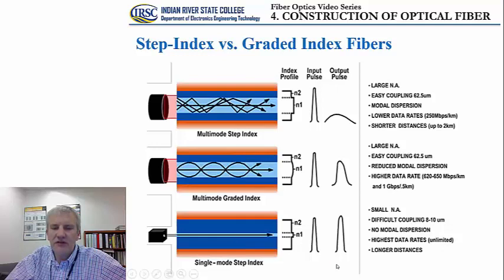The simple reason for that is that in the case of a single mode fiber, we have exclusively one mode, so the modal dispersion basically will not occur. However, in the case of the multi-mode fibers, we have multiple modes, and they have different trajectories in the glass core.